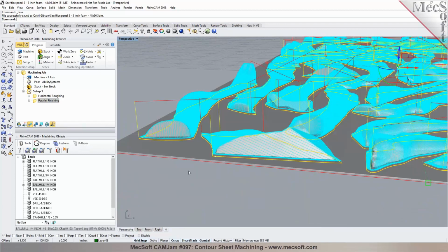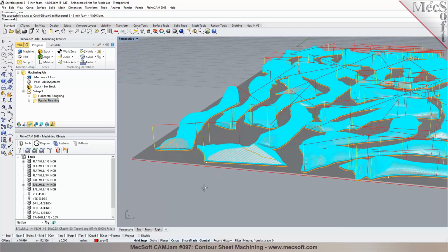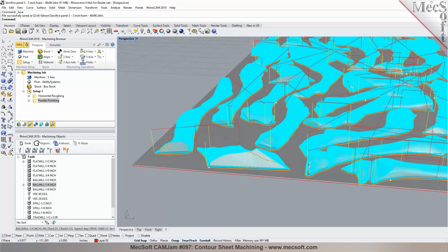Okay, so now I'm going to run a verification in here. I'm sure this is possible, but just to play it out, if we had a sheet that didn't have that bottom layer flat and it was just the parts, you can tell the cutter to stop like 15 thousandths above 0, and it'll just stop there, right?